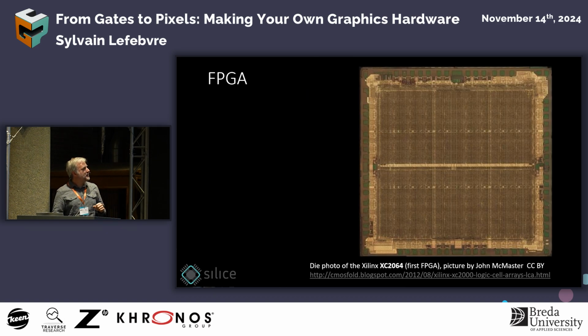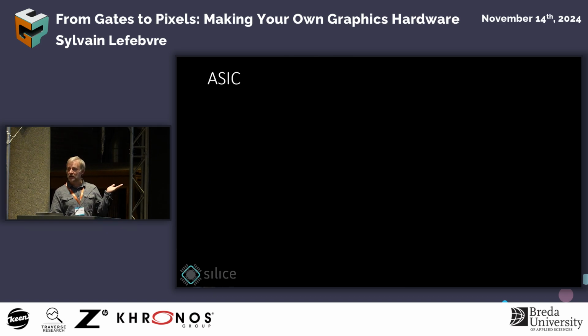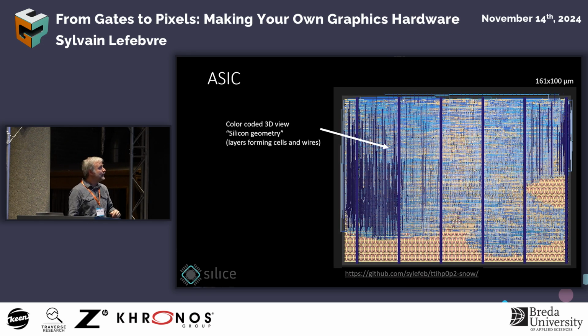All right, so this was for an FPGA, and now just a quick note on ASIC. If you want to do this on an actual piece of silicon, well, it's the same. You have to go through a different toolchain. Yosys is still here, but the rest of the toolchain is different. And it will output a blueprint for your chip that you can send to a fab so that you get your actual piece of silicon, right?